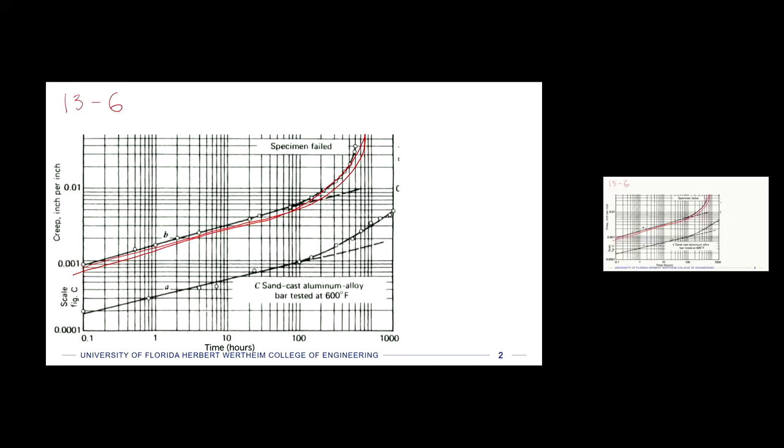A solid square support bracket of this material. So now we're not in the creep test mode, now we have our own part, 1 inch by 1 inch by 4 inches long and subjected to a direct tensile load of 10,000 pounds. So same conditions that this thing was creep tested at.